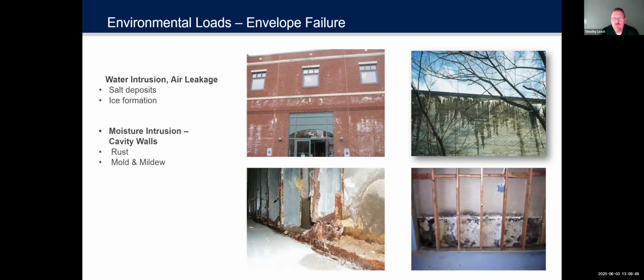In this case, water intrusion in through systems. Like we said, water vapor wants to move into the walls. If you have significant water intrusion, like you see here on the left, you can see these are galvanized studs that have been exposed to water for a long time. And of course, there's probably some minerals in that water that are acting on that galvanizing. And you could see that even though it's galvanized, there's a lot of rust here.